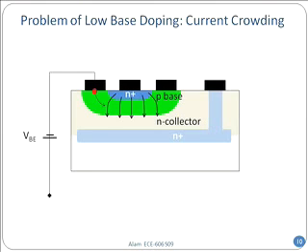Now think about it. I have applied a bias VBE between base and emitter, right? Emitter is in the middle. Base is where the red circle is, where the electrons are flowing in. Now, this electron comes in and essentially recombines or goes out through the collector or through the emitter, right? That is the holes coming in from the base contact, they come in and then through the reduced barrier go out through the emitter contact.